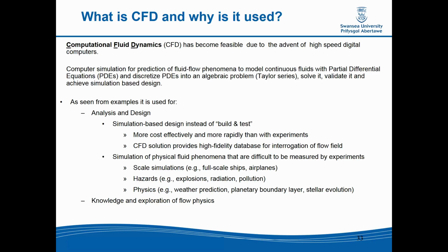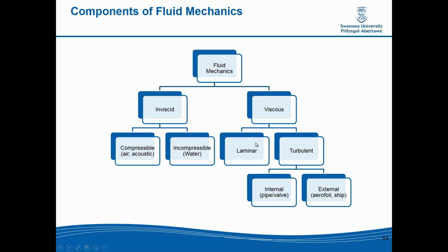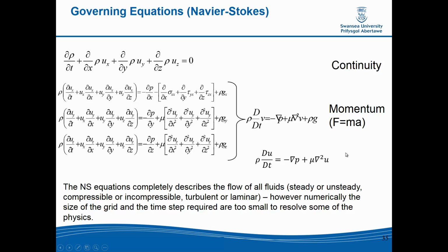I'm really not going to have time to go through all of this now, so you are going to be able to get the slides. I think you know what computational fluid dynamics stands for. We've been through it enough. I may have shown you this before as well. We have the breakdown of the fluid equations, the inviscid, viscous. You've seen those in the fluid tutorials. We'll have typically either a laminar, which is the default ANSYS setting for fluid, and then you'll have your turbulence models, and then you can apply that internally or externally and throughout the different boundary conditions you set.